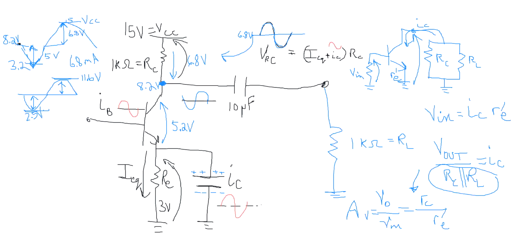This is the situation where we were pushing back on the current. The voltage is rising, which is stopping the collector current. And at that point, all the collector current has been diverted to the load. There's nothing going down my transistor. Is there any way to get higher current, higher voltage? Can I push past that 11.6 volts?